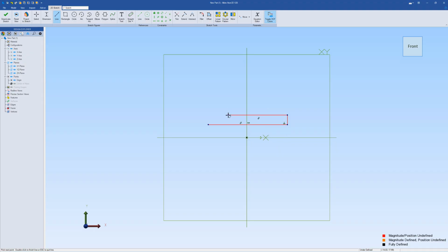I'm going to click again, move up and get that perpendicular snap. I'm going to come across to the left, and when I get in line above the first point we started with, you get a little red guideline. That's just to say those are lined up, and I've also got the perpendicular snap there, so that's what I want. I'm going to click, and then I'm going to go down and close the shape and click on that first node we created.